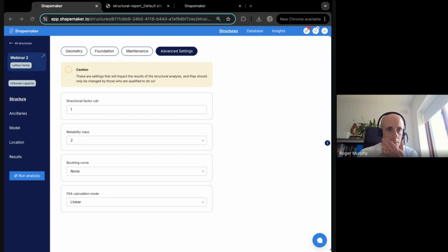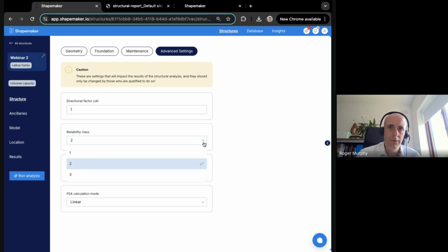I do clearly remember learning everything about reliability classes and design life. In a way it's straightforward, but it's so fundamental. With that drop down you just selected there, it's a big choice, and that's really something that should be done between the asset owner, the customer and whoever else is involved.